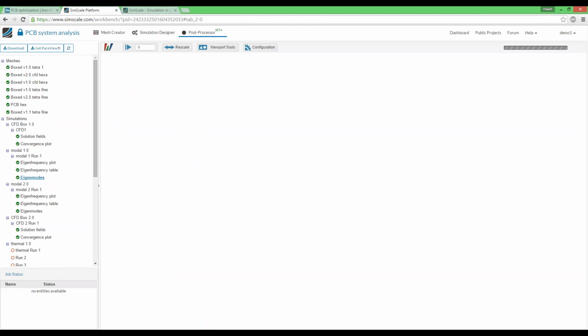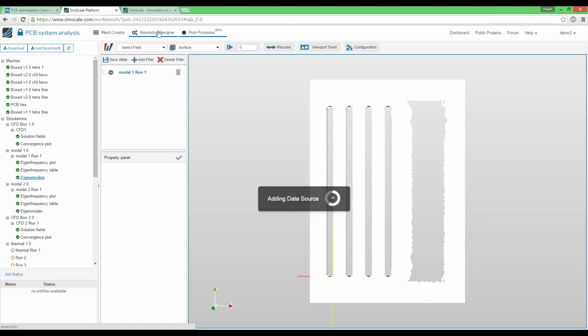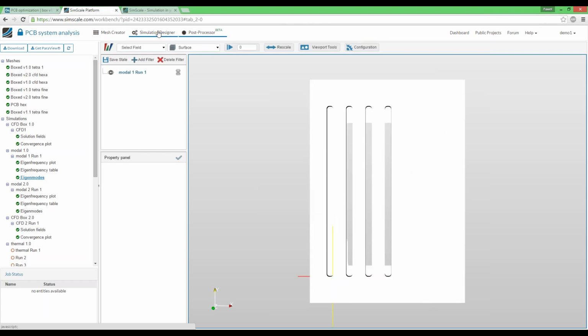We have another question. What is the name of the solver performing the calculations in the background? And are hex elements supported? The solver can be seen inside the simulation setup. I'll jump there after we load the post-processing window. Hex elements are supported, but unfortunately the meshing tools here do not let you mesh for structural analysis. You can use hex elements for fluid dynamics.